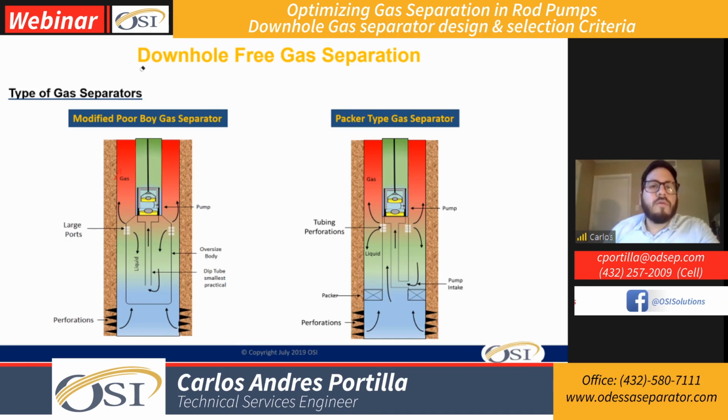Because we have a bigger ID, we will have a higher reduction in velocity inside. So it will be easier for the free gas to flow upwards and then be purged by any outlet point that the gas separator may have.